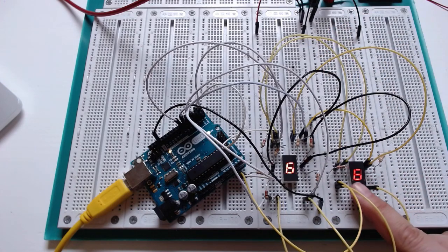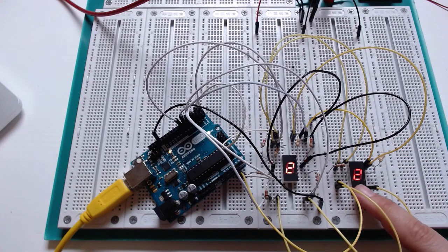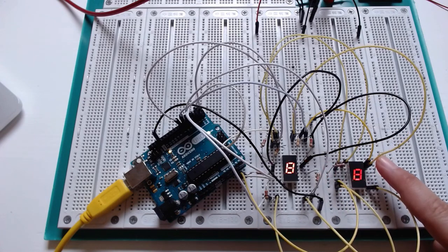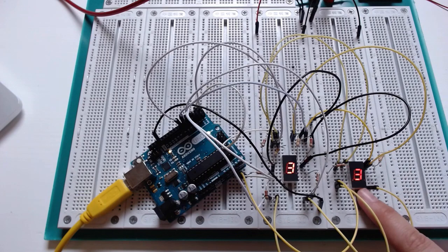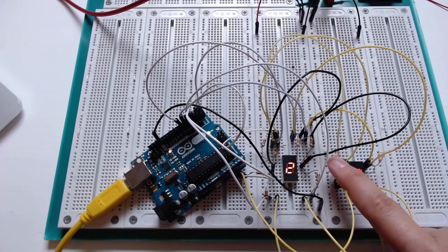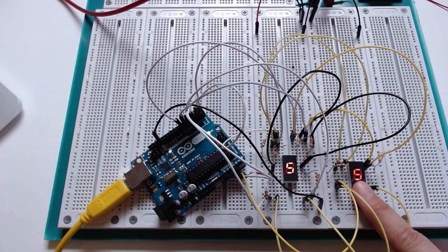In this situation, I have two commons, so I probably have about 4 or 5 LEDs being driven by each one of these common cathodes, which means that depending on the numeral that's on, I'm going to have a different amount of brightness and a different amount of current flowing through these current limiting resistors. Now, this might not break, this might not melt, this might not be physically damaging, but it's incorrect.